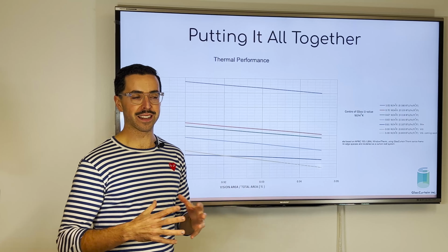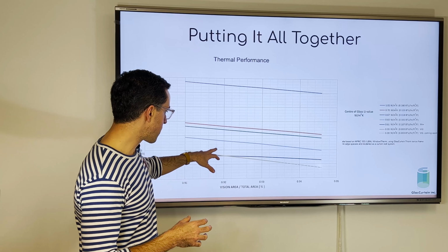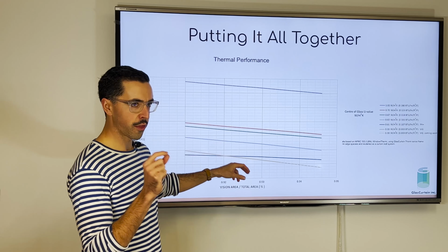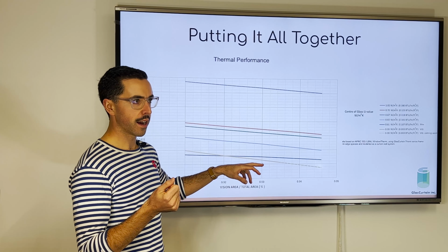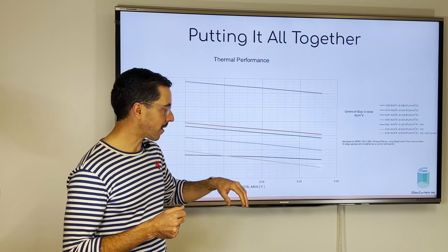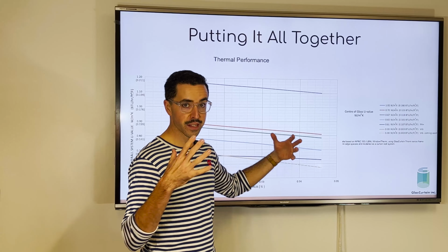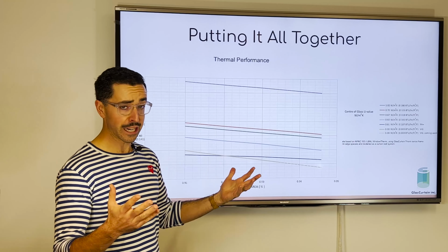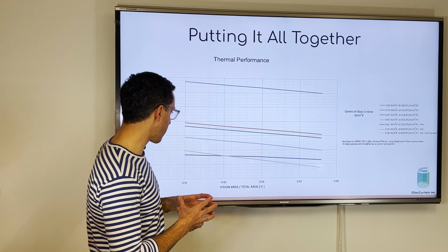We're using vacuum insulated glass on a new project actually in Edmonton, upcoming, and it's going to be 34 millimeters overall thickness with a center of glass value of 0.4 or 0.39 watts per meter squared Kelvin, which is this yellow line here. And the sizes of these pieces of glass are only increasing. So that's why we have this dotted line over here as that manufacturing technology improves.